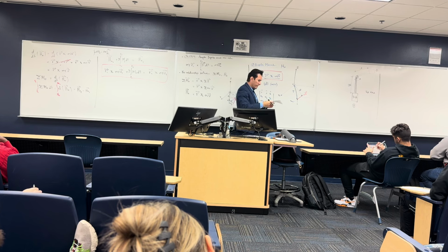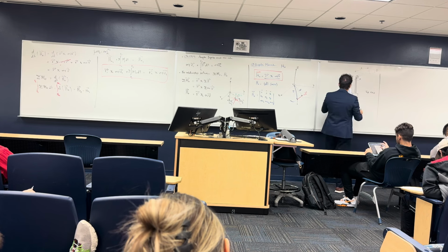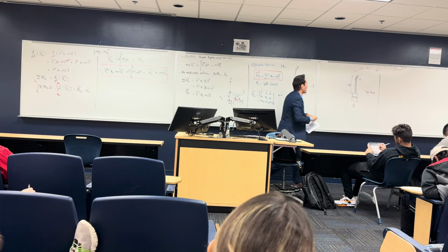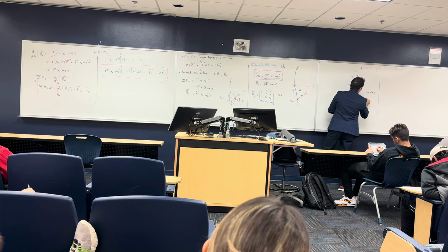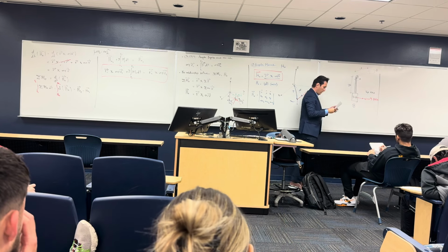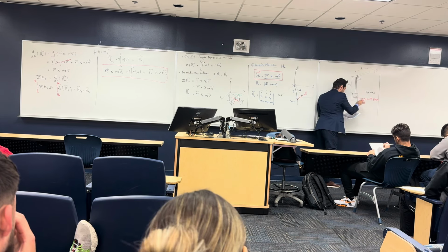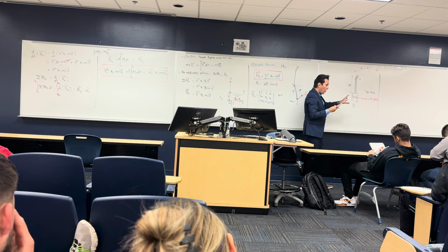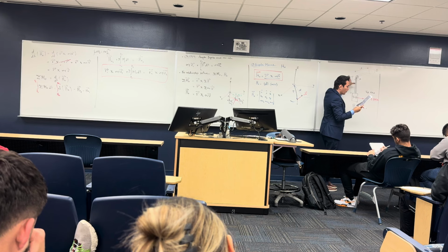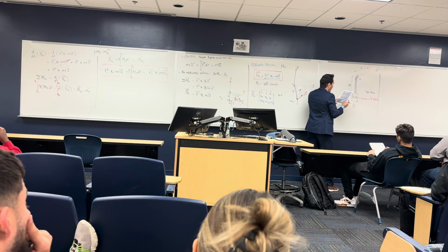All right, so it says here that the crate is moving around a frictionless assembly line at position 1. The crate is moving with V1 of 0.5 feet per second, and V1 is something like this, in a straight path, okay? Just after, an arm begins pulling the crate from R1 at 2 feet, with a constant radial velocity, VR of 0.4 feet per second.